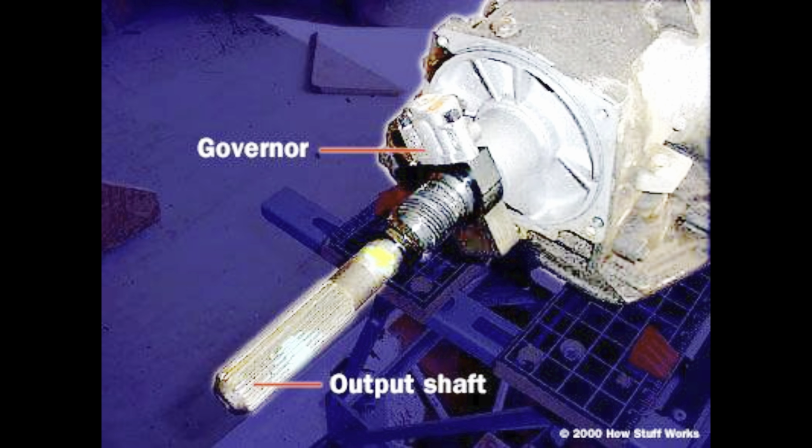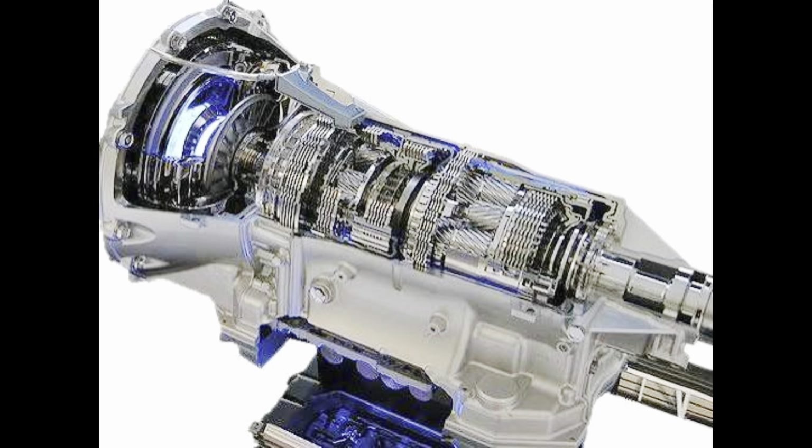A seal is usually made of neoprene, similar to the neoprene in a windshield wiper blade, and is used to keep oil from leaking past a moving part such as a spinning shaft. In some cases, the neoprene compound is assisted by a spring that holds the neoprene in close contact with the spinning shaft. A gasket is a type of seal used to seal two stationary parts that are fastened together. Some common gasket materials are paper, cork, rubber, silicone, and soft metal.